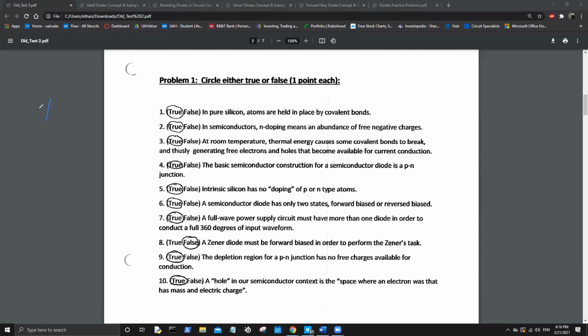All right. So let's say we have a positive charge and a negative charge. Here's your P-type section. Here's your N-type section, right? Now we're going to apply an external voltage onto the system. You tie your positive over here and you tie your negative over here. Your high voltage, low voltage. What happens? Electrostatically, this repels. These systems come closer together, and then they can allow charge to conduct. It closes up that depletion region and allows stuff to flow.